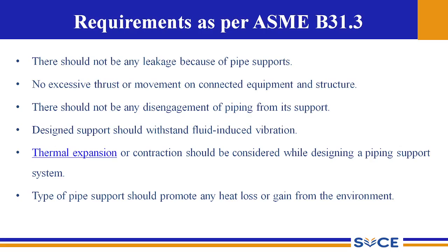Next is to withstand fluid induced vibration. When the pipelines are transporting fluids at a high velocity, there can be cavitation happening because of throttling or because of water hammer effects. The designed support should withstand all the fluid induced vibration when the fluid is hitting on any pipe bends or elbows, or the change in direction of the pipe routing. In all such cases, the fluid will hit the pipeline with greater velocity. So this will induce vibration, and all the designed supports should withstand the fluid induced vibration.